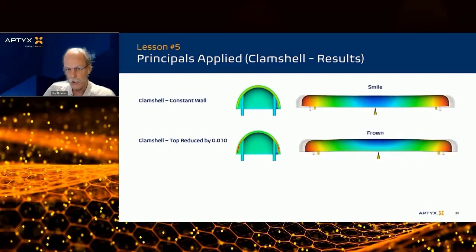So I can actually go into the tool, put this shape in, build it, run it, and then tune it into the flatness coming off of the tool for my final move. So it's steel safe, the core standing high, and we can take some off of it. So this is where you really want to get to if you can.